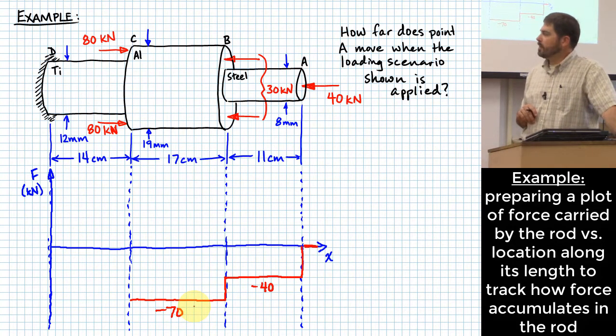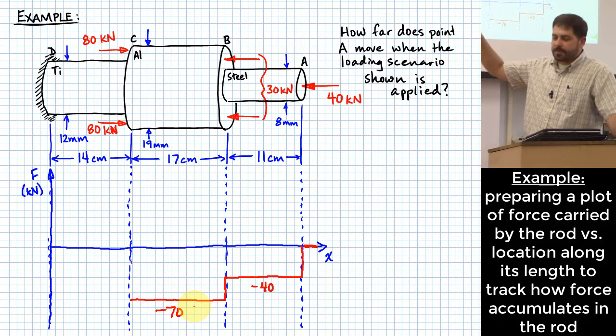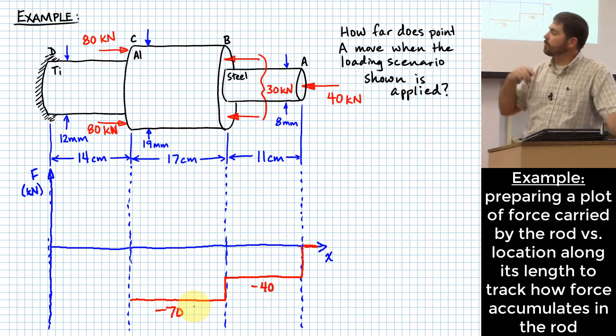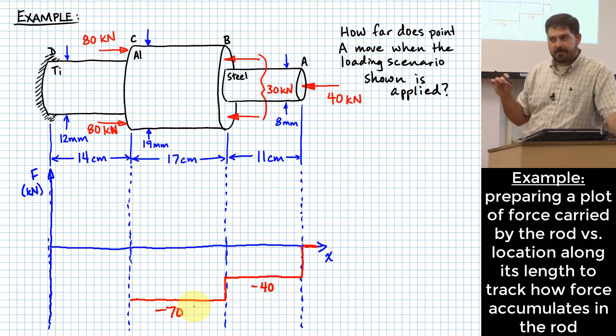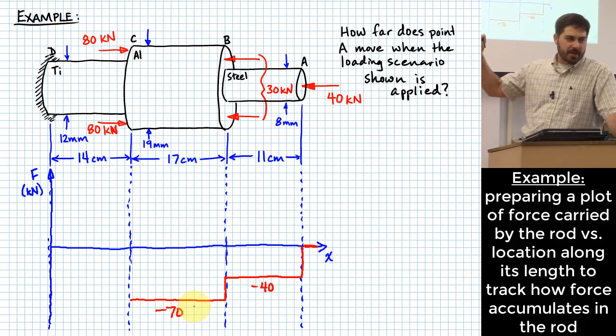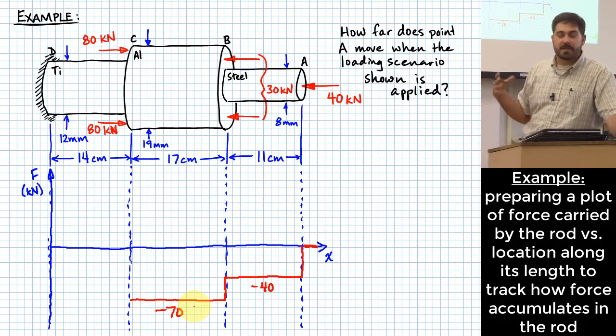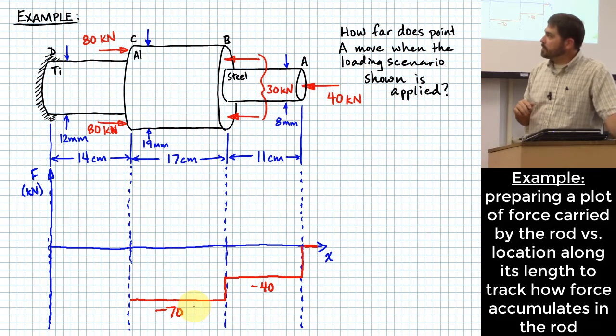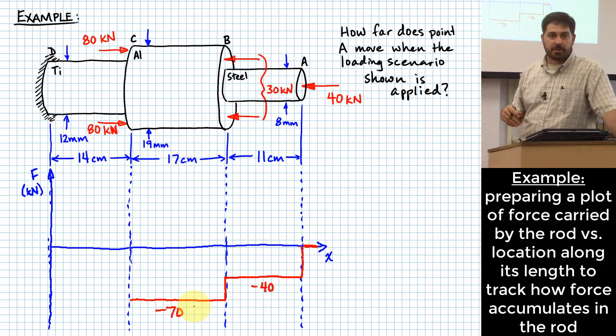Now contrast that figure with the bracket across the two forces with another one here where I show two forces, each of them labeled 80 kilonewtons. What do you think is a good way to interpret that? That is 80 kilonewtons each. I'm trying to show you some of the tricks about how some of the problems you might see are written. You have to make sure you interpret it properly, and it makes sense that it works that way. I just wanted to say it so that you'd hear it. But I've got 80 kilonewtons each, which means it's a total, someone said, of 160 kilonewtons.